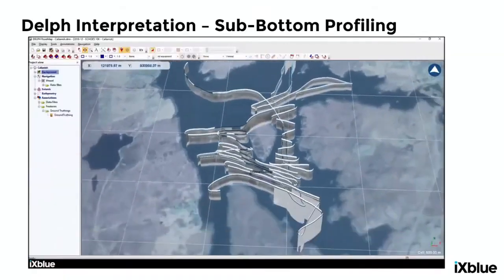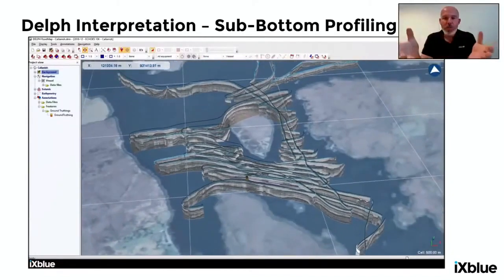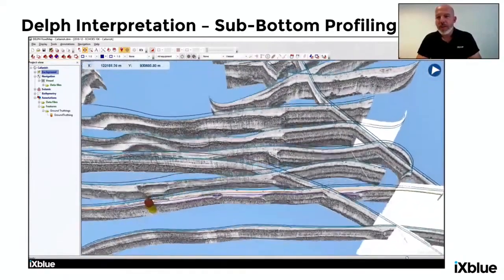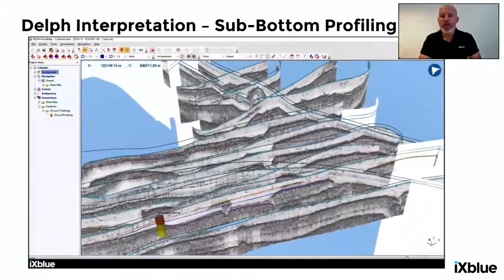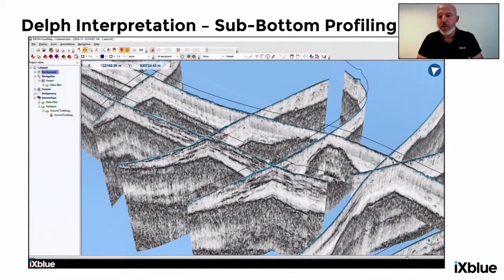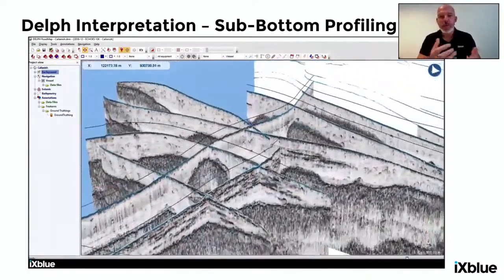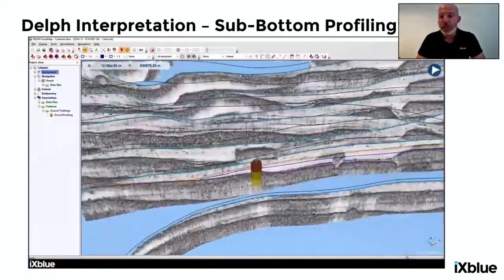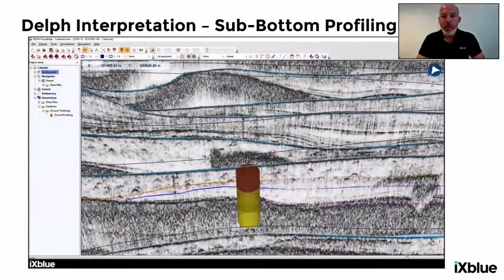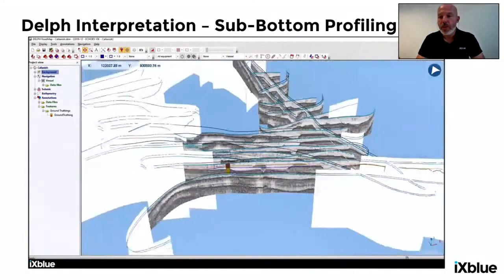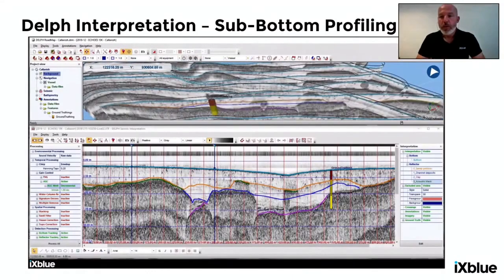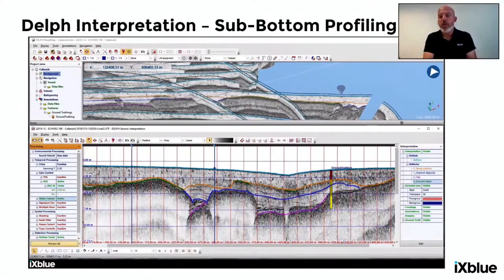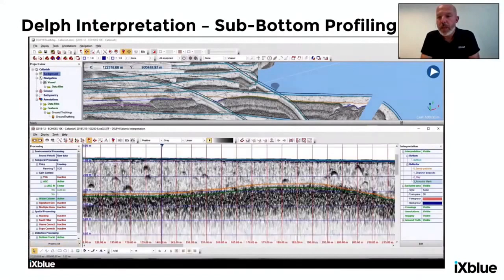Yeah, so you will see a second project. We start from the same Roadmap software, so this is not individual software, it's all working with the same core parts. Within the Roadmap software, what we see is the track plots and the georeferenced sub-bottom sections. This is something we provide like we do the sonar mosaicing, so we create very quickly these 3D fence diagrams. You can import external data like core logs that you can overlay onto the 3D, but also onto the sub-bottom profile, to correlate the reflector interpretation together with the ground truthing data.